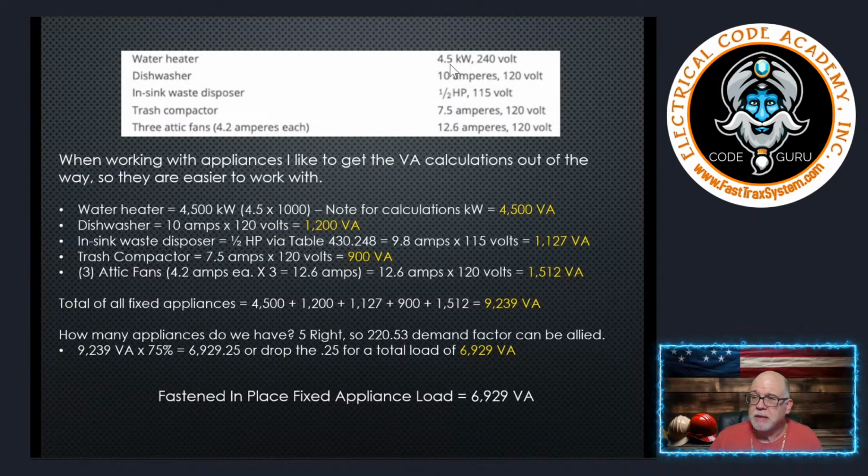And we're not talking about a hot water heater that's gas that has a blower. That would typically be just a 15 amp branch circuit to a receptacle. It doesn't typically even have to be dedicated. It might be one of those receptacles that are down there for the 3 VA per square foot. It might be just a general use receptacle you plug into. You've got to look at the instructions from the manufacturer to see whether they call out something dedicated or not.